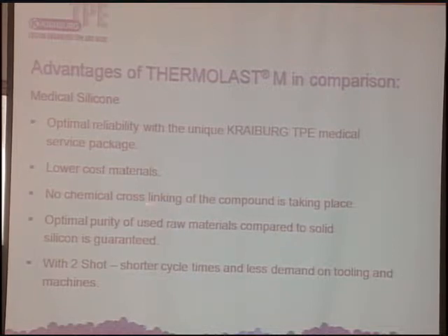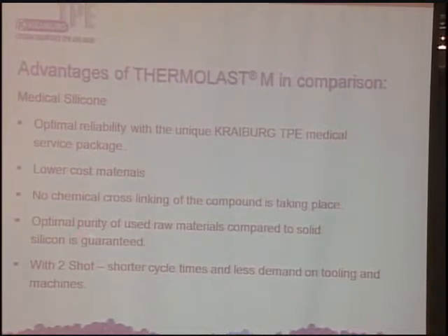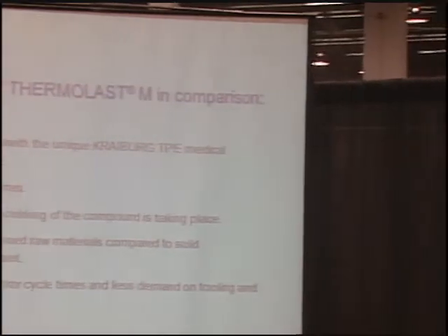Here, obviously, there is no chemical cross-linking, so the material has optimal purity as compared to the silicone materials. And also, it's possible to do 2-shot processing, so the cycle time is much shorter, and the demand for the tooling and the machines is also much easier to meet than the curing and the processing of the silicones.